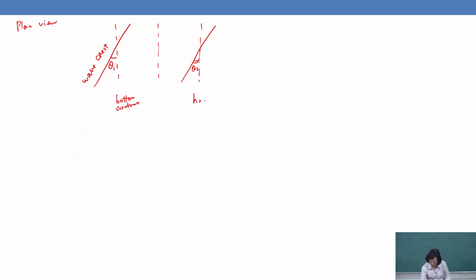And over here, H2 is 3.5 meter, and here is a dip. So we don't need to write the figure. So we are using the Snell's equations and the refraction, shoaling equation. We will have H2 equal to H1 times Ks and times Kr.